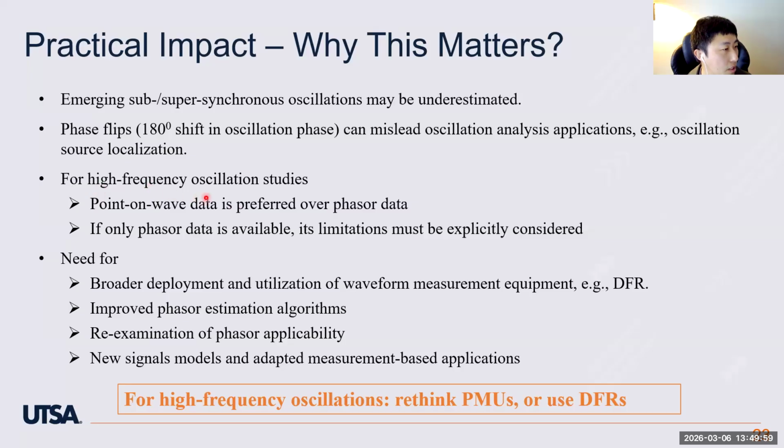For high frequency oscillation studies, we should use point-on-wave data. If phasor data is the only data available, the limitation must be considered explicitly.